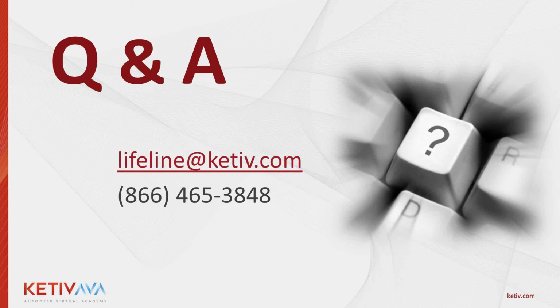Let's see here. First question is from Jason Mays, and the question is, I don't think virtual comps can be vaulted. Is this correct? Let me reiterate to make sure I understood it correctly. When you create a virtual component, I think the question is, will that component be vaulted? The answer is no. It won't actually create a component inside of Vault. However, if you're using Vault Professional, it will recognize that you have a virtual component, and it will create an item for you if you want to.